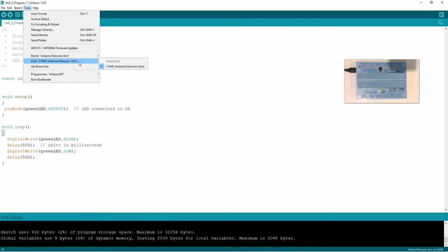Now, if you're using a laptop, you might see a few different COM ports show up, maybe COM1, for example, and it should have this text. If you do not see this text, you can unplug the USB port, plug it back in, and check to make sure that it's working. Okay, so now we're actually communicating to that board.